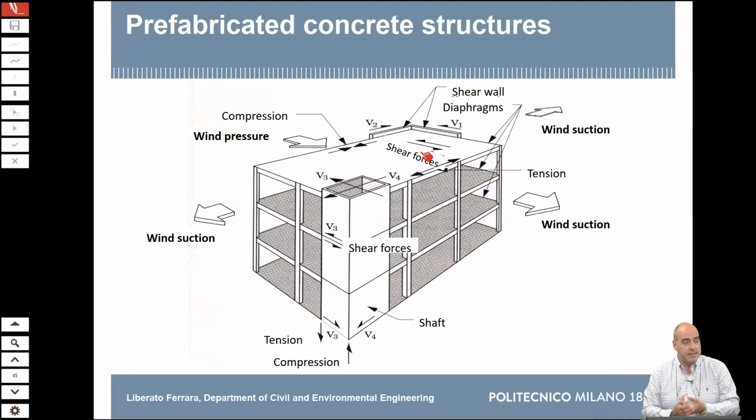And the issue is, as I was saying before, first of all, how do we guarantee the diaphragm action of a floor deck or of a roof deck, which can be discontinuous? The other thing, since we might have different elements, is how do we distribute the forces among the different elements? And consider also that lateral forces are not only forces.